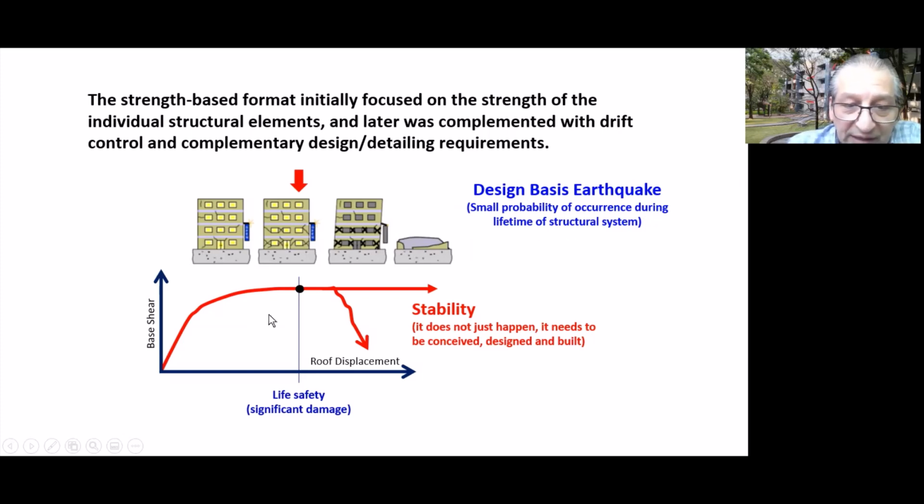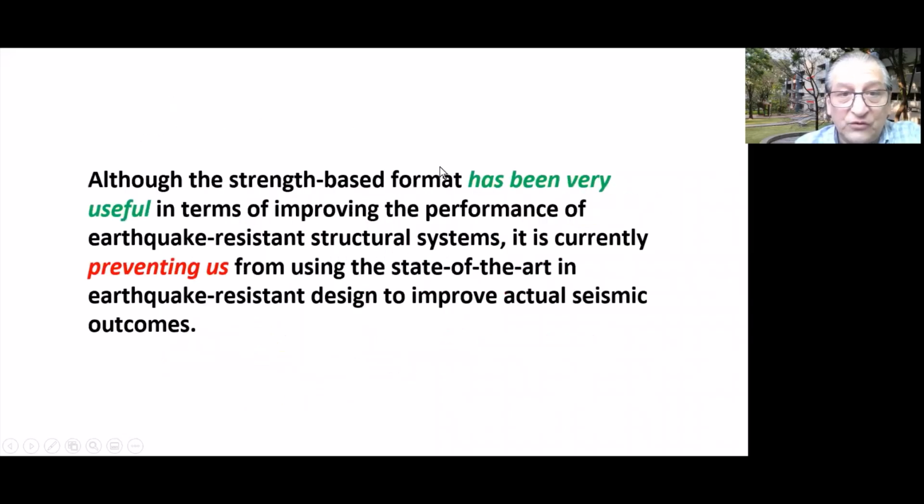And why do we accept this significant level of damage? Because of money. We thought that trying to control the lateral deformation of the structural system to smaller values to achieve less damage was too expensive. And given this small probability, it made sense to us at that point that we should allow for these large deformations within the force-based format.